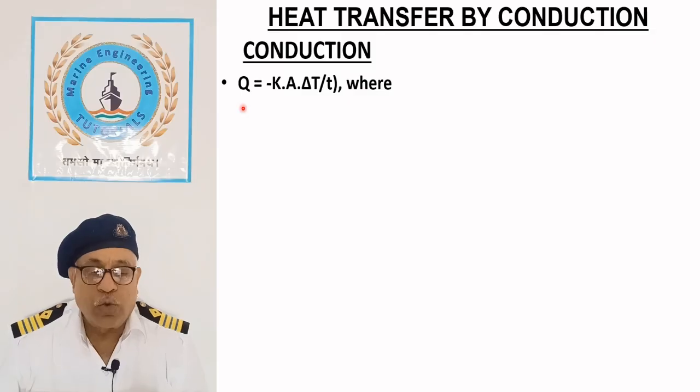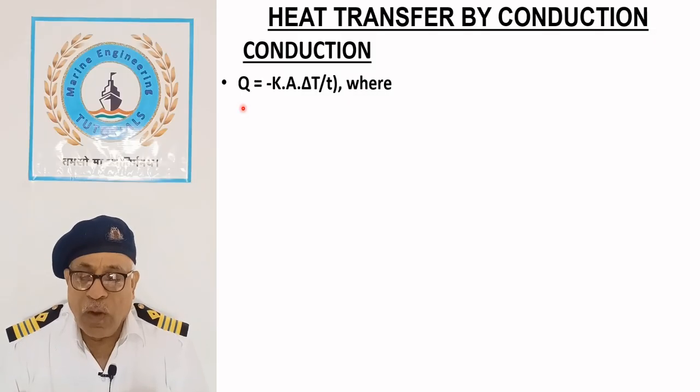Heat transfer through conduction is governed by Fourier's law, which states that the rate of heat transfer through a material is directly proportional to the temperature gradient and the cross-sectional area, and occurs in the direction opposite to the temperature gradient.